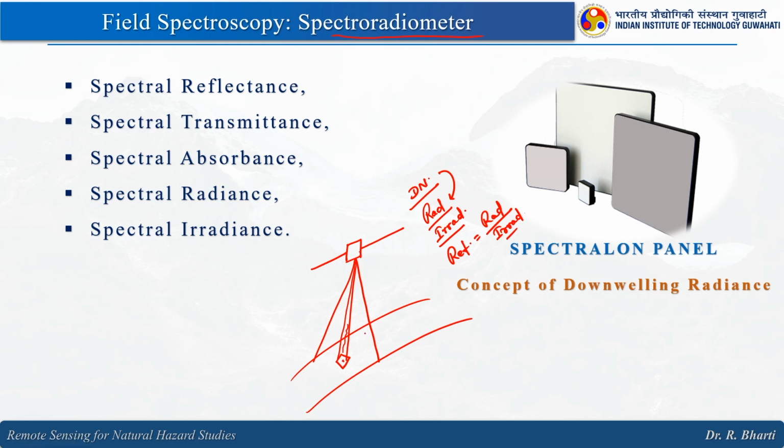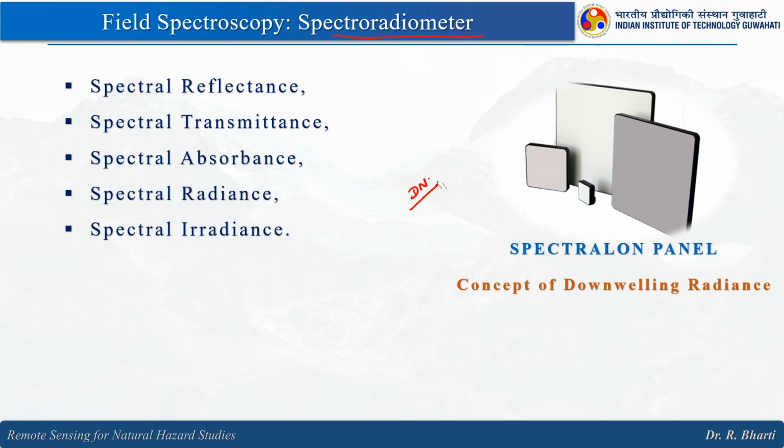Once you have the irradiance, then we calculate the reflectance, radiance by irradiance. So, here if we have the same instrument, we can put it here over the ground focusing towards the sun, because the sun is our source of light in this condition. So, this will provide you the irradiance, right. But this is not possible because these instruments which are sent to the space are different, and the same wavelength you can measure with a different instrument, but different instruments will have different problems and advantages according to their detectors or the configuration.